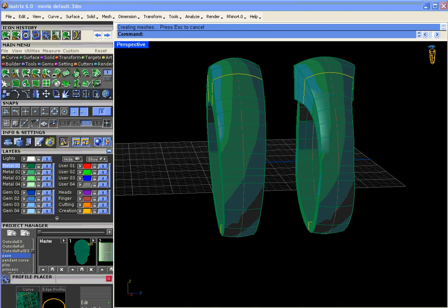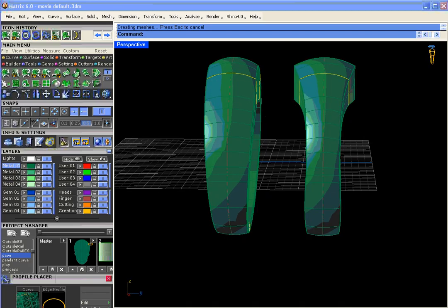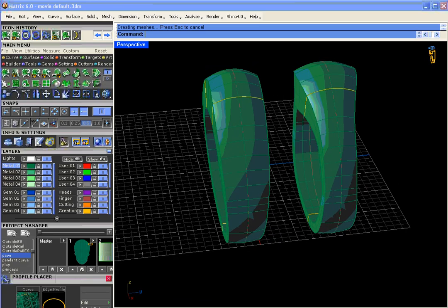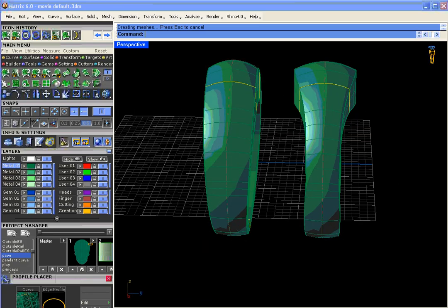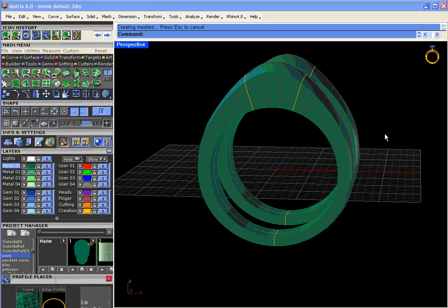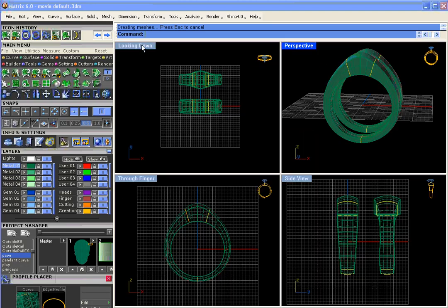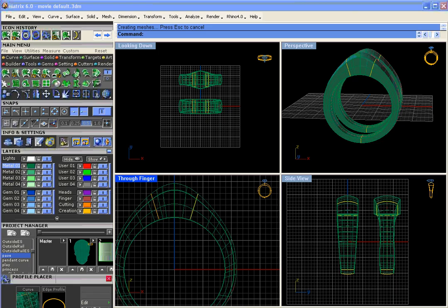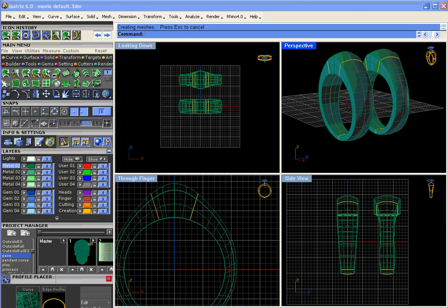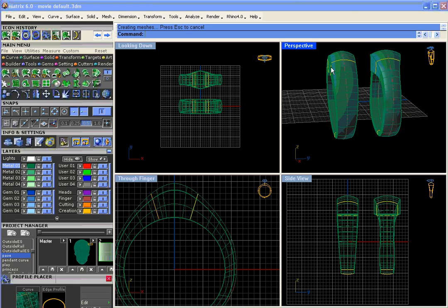The maintain height option keeps a nice flat edge here. Having maintain height unchecked gives us this more feminine curve, which also can be very desirable. Okay, and what's going on here? Maintain height basically says, hey, when you go down this section, I want you to draw a straight line right along here so that it's perfectly straight along the edge.